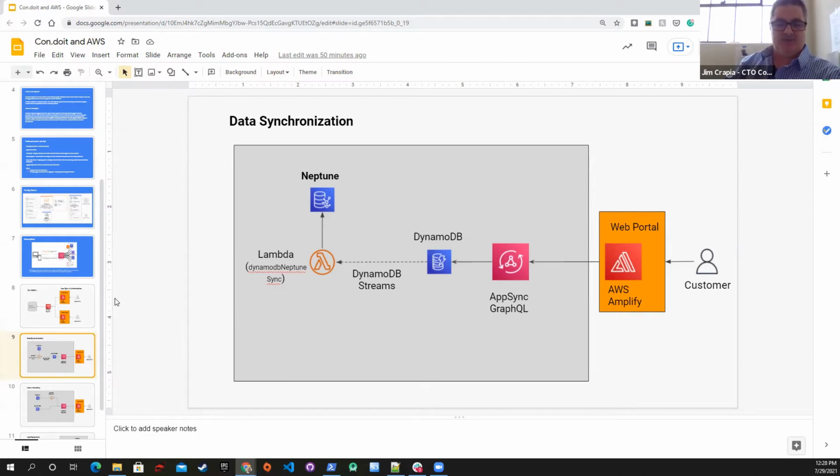Going back just a little bit, remember I first showed you guys the electrical single line diagram that we had? That thing is kind of like a family tree, right? You've got your service from Alabama Power, whatever, maybe some generators, and then there's some equipment hooked to it. That equipment branches into other equipment, to other equipment. These can get relatively large, 300-400 pieces of equipment with a tremendous amount of detail, but also the raceways, the conductors, everything that connects two different pieces of electrical equipment.